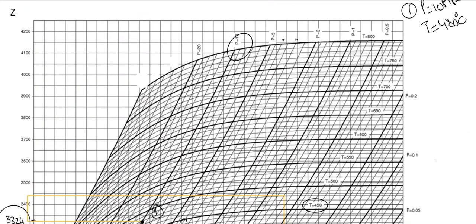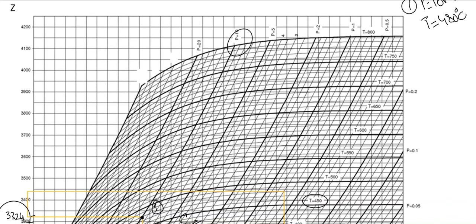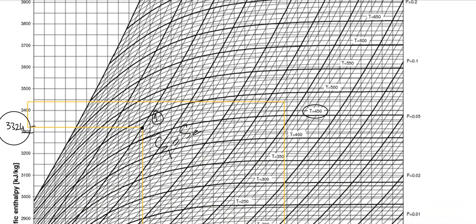So now moving to this HS diagram again. 0.5 is over here, 1 is over here, 1 megapascal is here. So let's count it again: 0.5, 0.6, 0.7, 0.8, 0.9, and obviously this one. So the second line over here seems to be 0.7 megapascal.